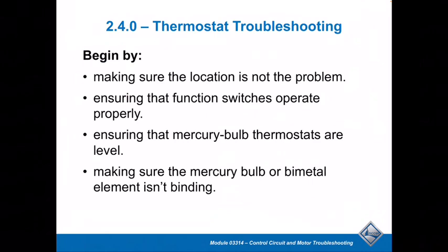So, all right. Let's take a look at some of the troubleshooting side of things a little bit. So first of all, thermostat troubleshooting. First thing, you look at where it's located. Is it a good location? Is that creating some of our issues? Are the switches set? Is it programmed correctly? That isn't as simple sometimes to go through the programming, because you may have to find the book to be able to do that on some of these thermostats, because there might be a code or a certain sequence of buttons to be able to get into it.